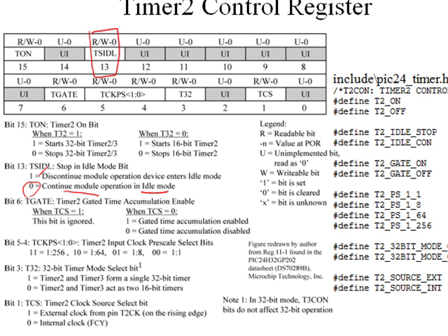If we program this bit to a 1, then we can actually turn this peripheral off when we're in idle mode. We're not going to care too much about the setting of this bit in our examples. We're going to keep it at 0 for our examples. This bit right here, the T-gate bit, we're not going to discuss this mode of operation. We're always going to keep it at 0, which means that mode is going to be disabled.